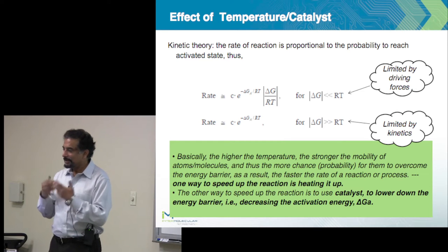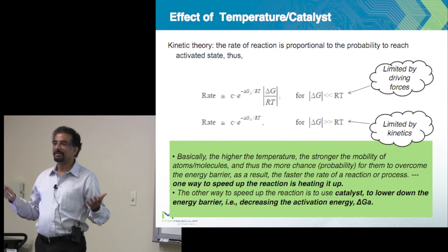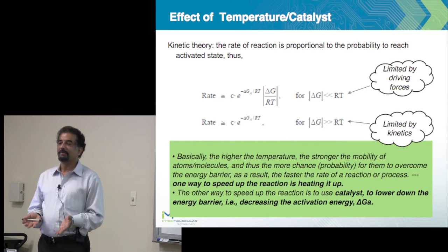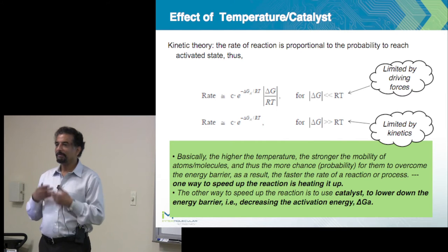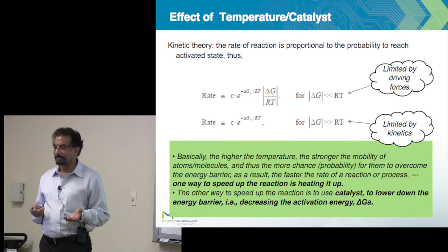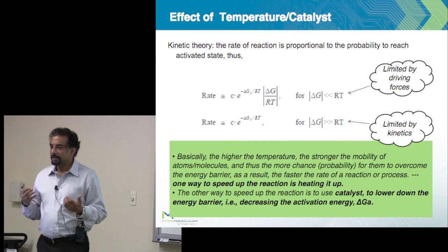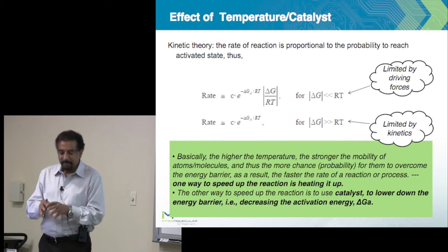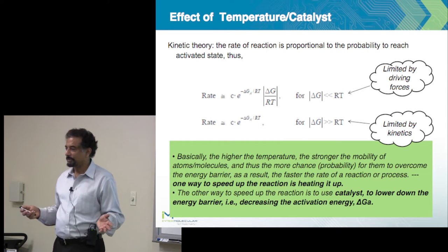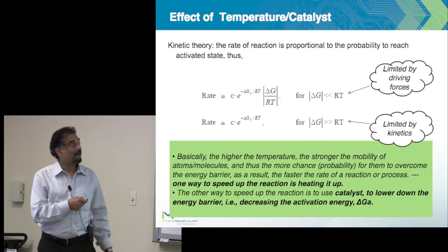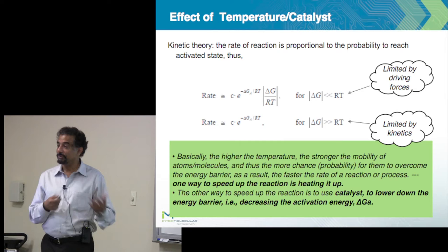And in most of the silicon processing, that's what we've done in the past. We've always raised the temperature whenever we wanted something to happen. But in many cases, the transformations or the depositions or the materials underneath can't stand those temperatures. So you have to figure out how to reduce this. You can reduce it by catalyst.